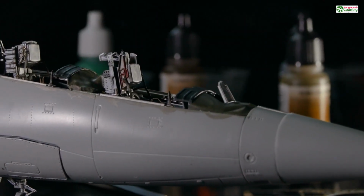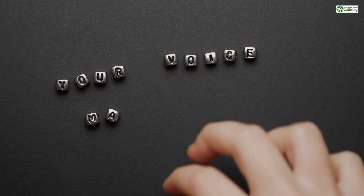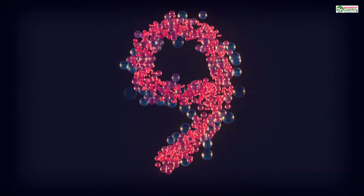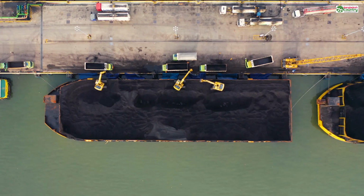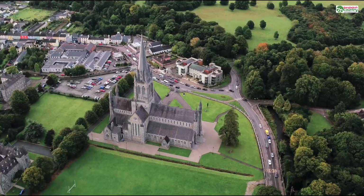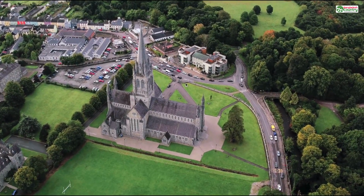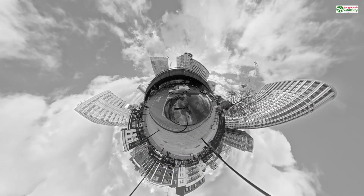If you have set up your scene units and modeled to scale correctly, this number should almost always be 1.0. Setting it to 1.0 means export it exactly as it is. Don't change it unless you have a very specific reason and you know exactly what you're doing. The second, and arguably more important, setting is a little checkbox that might say apply modifiers, or more critically, apply transform or apply scale. You must check this box.